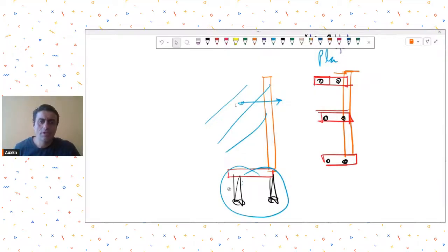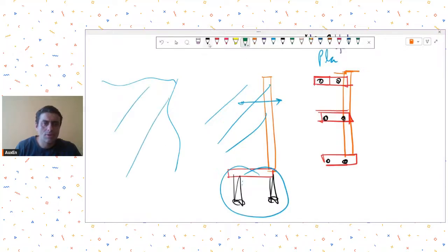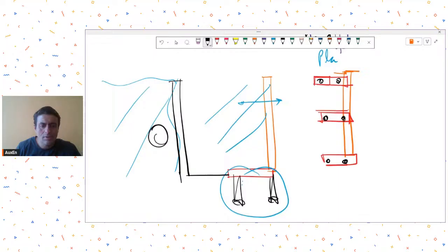Other possible configurations can be, maybe, if you are able to provide, let's say here is your fill, and this time let's say because of some configuration you are able to provide a wall over here, but you are not able to access this side. So in that case you can have arrangements like this. In this case, if you are providing piles, the piles will be under compression, right? Because the overturning moment is like this and it will create compression in the piles. So you can think of this type of an alternative also.